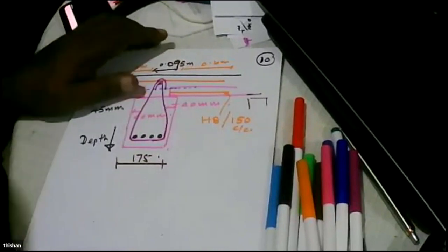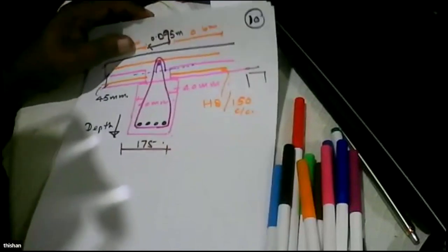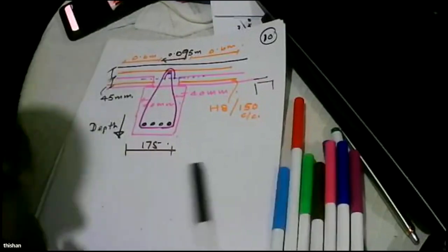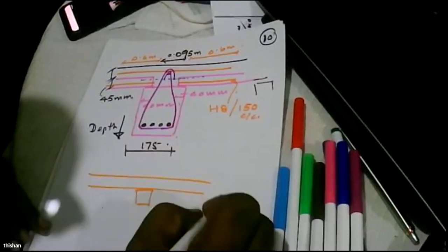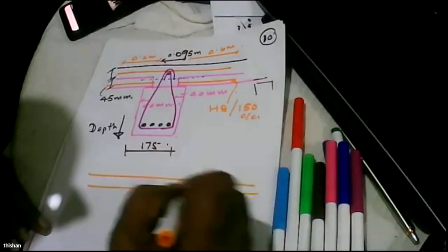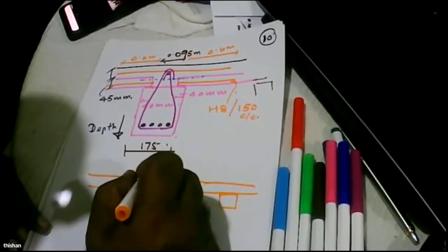There's a question. Is there any special slab arrangement under the partition walls, either in X or Y direction? Actually, partition walls are not a problem at all, because if you have a slab, beam, and another beam, and you are not sure of the slab capacity, the beam has to be designed for the partition load.